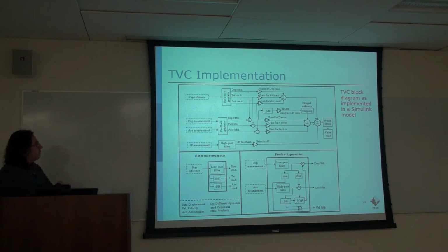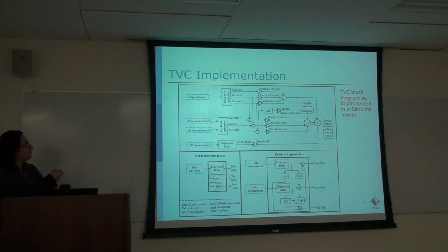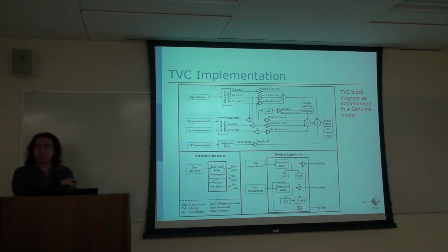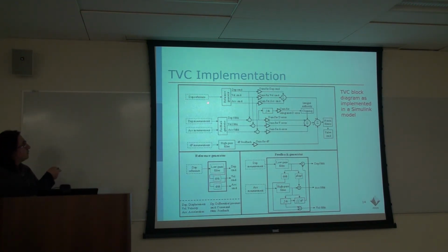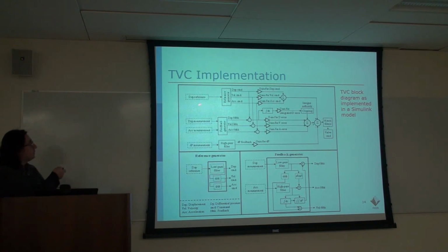And the input to these gains is the errors, right? And error is the difference between the command and the feedback. And this error is for the displacement, velocity, and the acceleration. So eventually we need to have the commands for displacement, velocity, and acceleration, and the feedback. And for that, you only have one command, in terms of one of the parameters.